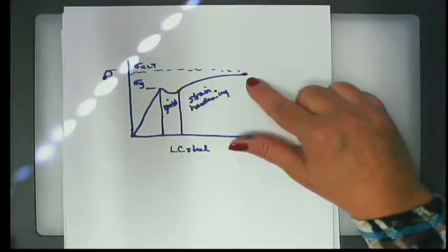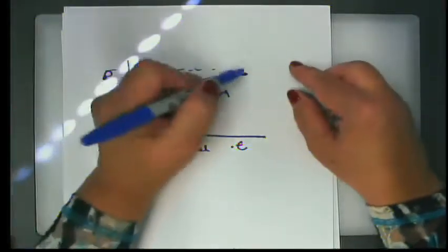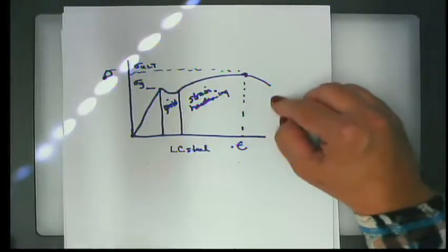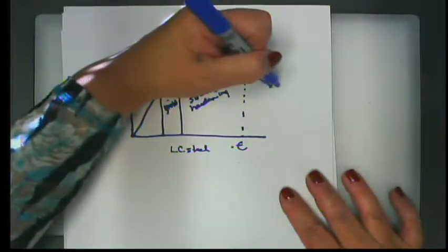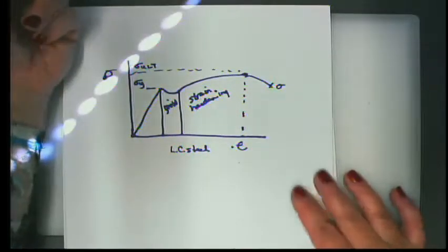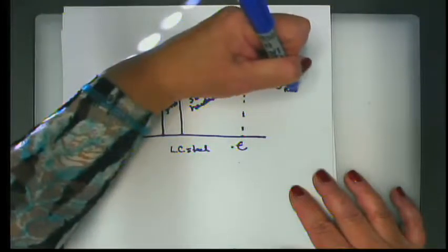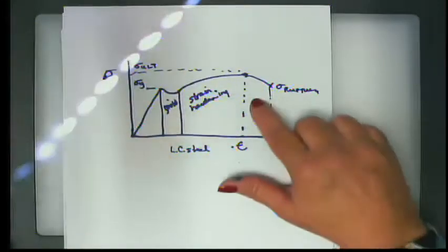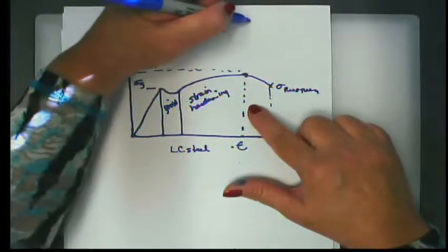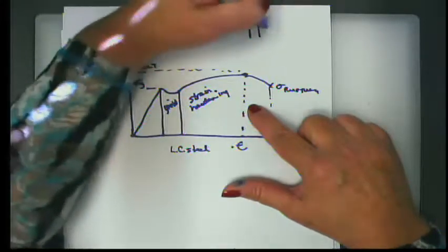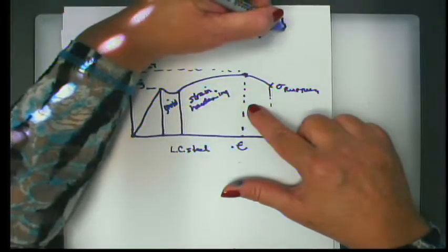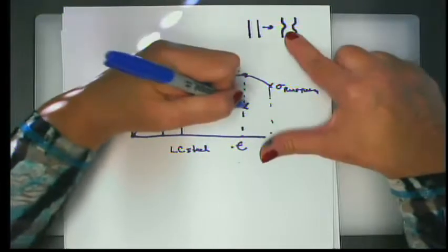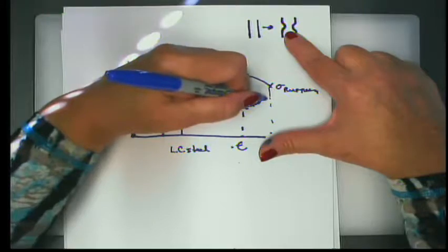And that's the point where it will not take any more stress at all. And then you'll see this curve start to decrease, and then it will finally rupture or break at this point. And the difference between here and here, this is where, if you continue to pull on a section that looked like this, it will actually sort of develop a little neck. And so it gets actually narrower. And so this region is referred to as necking.